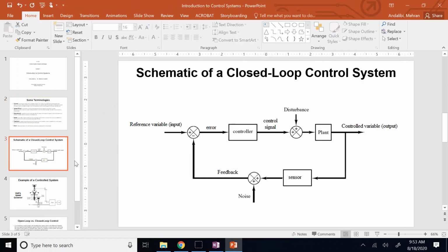But do we send that noise directly to our controller? No. In the controller, we have some ways to reduce the effect of that noise. As I said, filters, passive filters or active filters, low pass filters. So we try to mitigate the effect of them. But can we separate this noise from the sensor in the first place and send a clean signal directly here? No. Each sensor has inherently some noise in it.